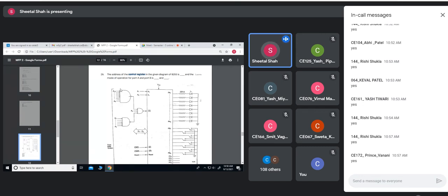As we know this is a NAND gate, if all the inputs to this NAND gate are 1, then the output of the NAND gate would be 0. Do you agree to this? So here the address lines 15, 14, 13, 12 should be 0, 0, 0, 0. Then 11 should be 0, and 10, 9, 8 should be 1, so 0, 0, 1, 1, 1 is 7.